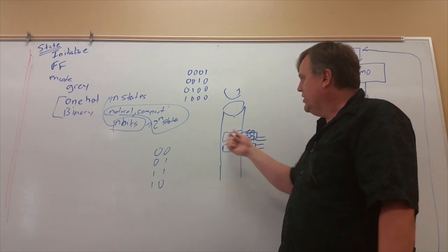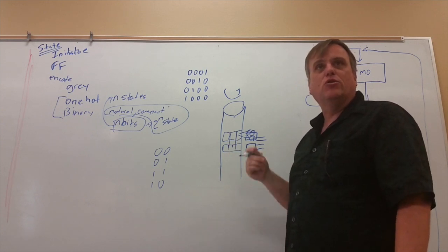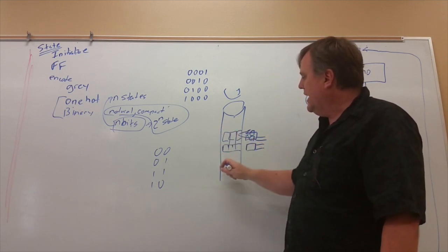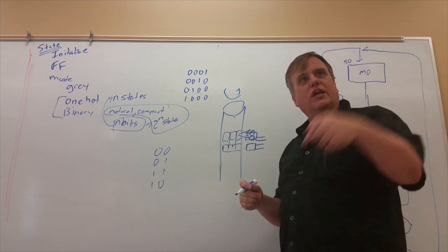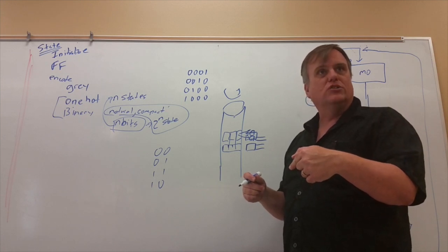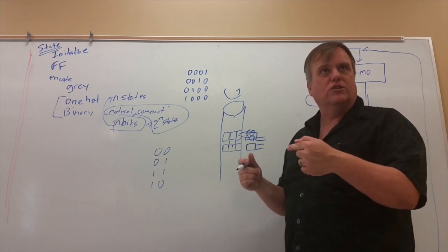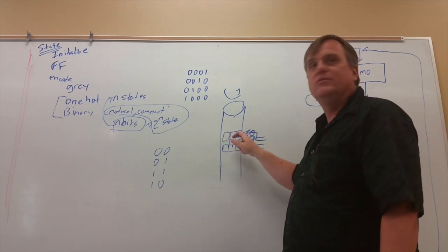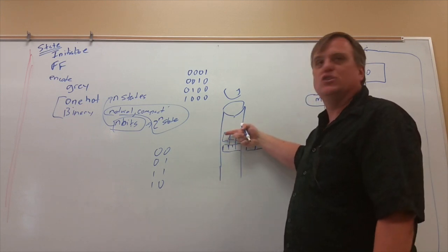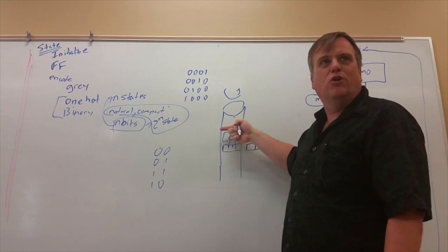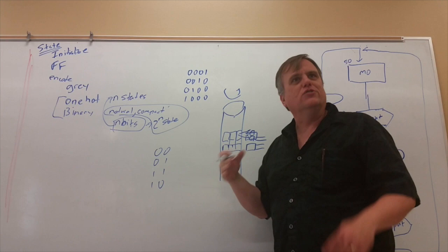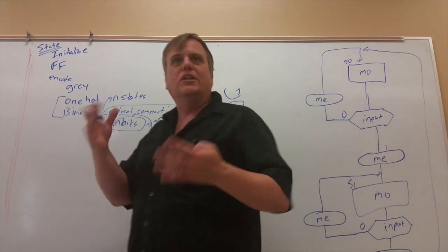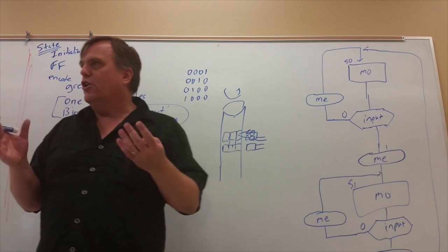And in particular, a really important one happens on these ones. If you've ever looked at these, they'll do a similar type of thing where you can put, as a real simple thing, if you've ever done a weather vane, you can have a metal vane. You can hook that metal vane to ground, for instance, or some low voltage signal. And then on this, you can put tape, which is an insulator, and then you just put a spring resting against it. And as it rotates, if there's no tape, you get connection. If there's tape, you get a disconnect. And so it'll turn it into a high-low signal. So it makes a nice, simple little device for reading and encoding things out.